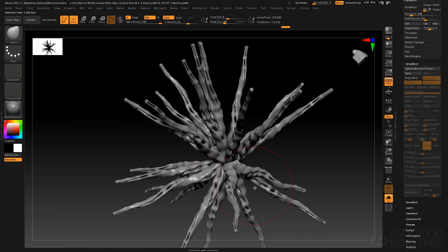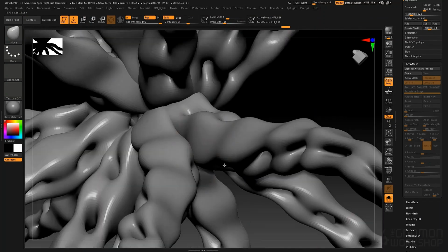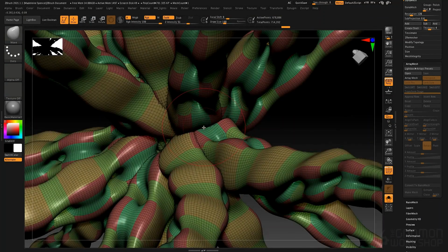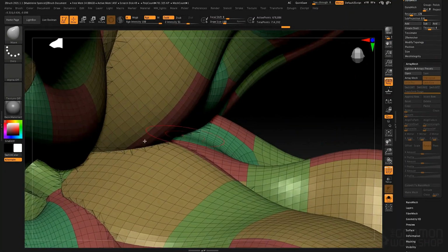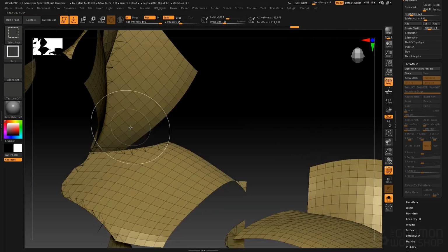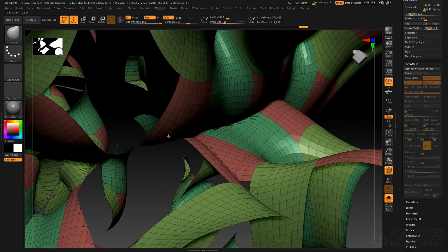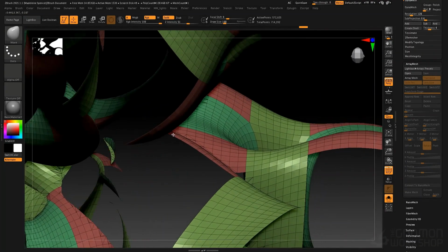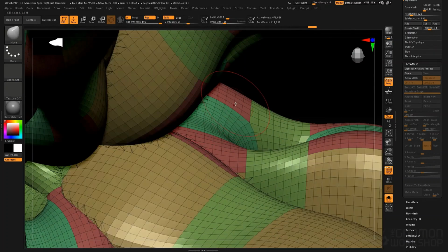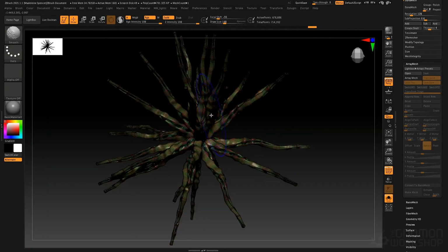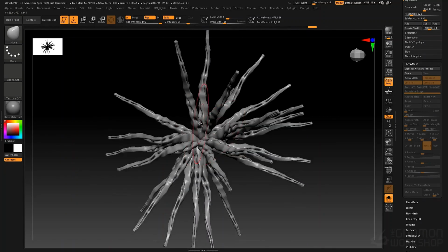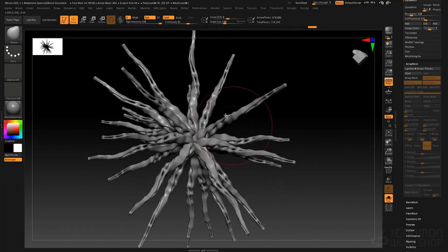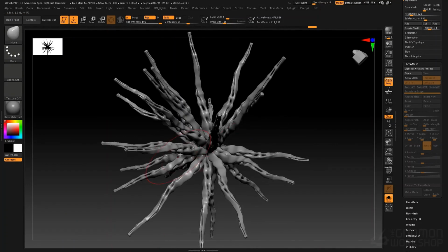So now if we zoom in here and then turn on frame mode, and we have to really zoom in for you to see it, these have now been stitched together as actual geometry. If I were to hide pieces and parts like that, you see there's nothing inside. It's all joined together as a single volume. That will facilitate allowing you to Z-remesh them successfully as a single object, and it also helps make a cleaner model for something like 3D printing, for example, or just working in general.